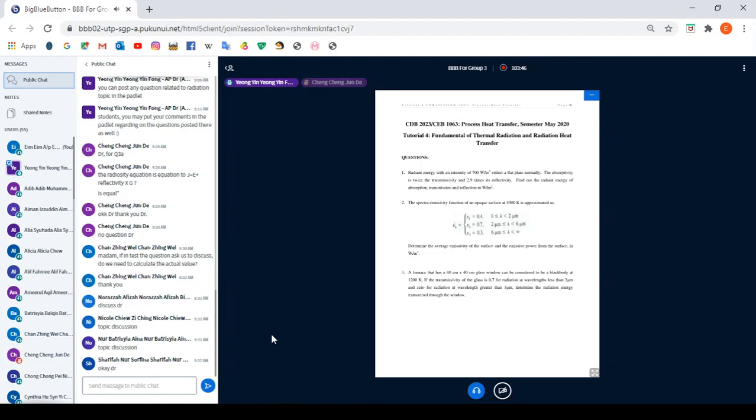Okay, welcome. Here is the question: what is the difference between LT and LH? You can look at the initial slides in chapter 8. LT is the thermally developed profile length, and LH is the hydrodynamic length, whereby the velocity profile is developed. And then what else? There are no more questions over here.